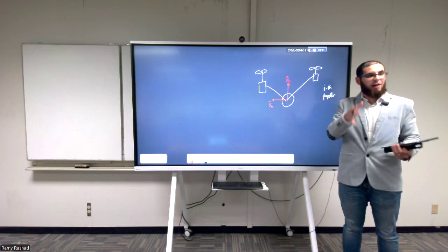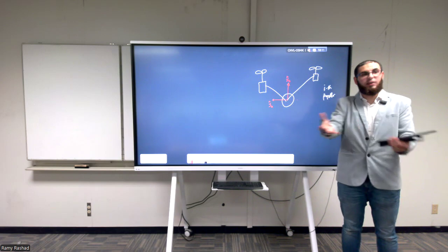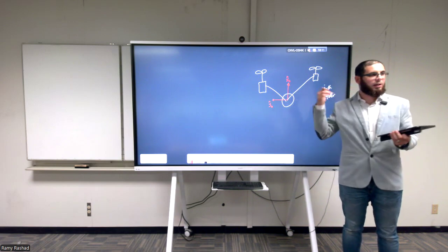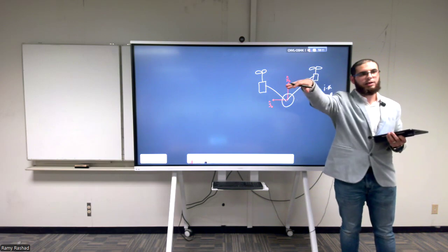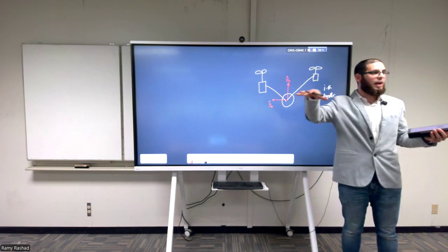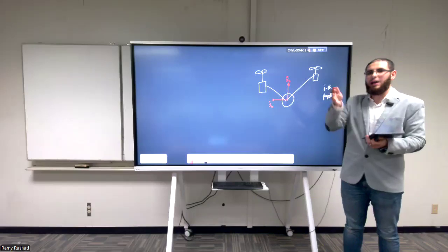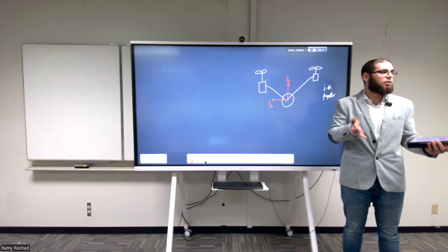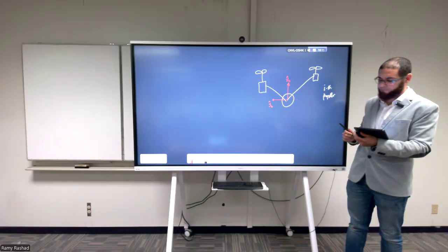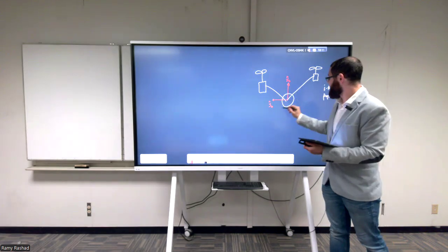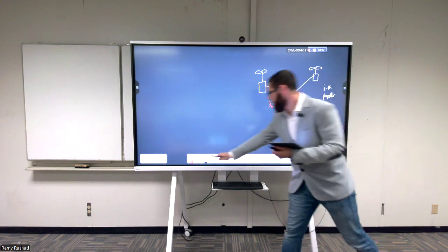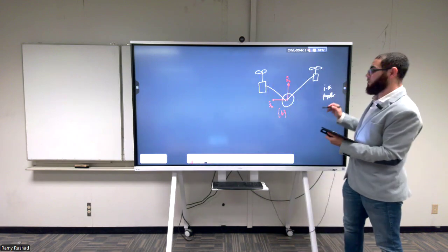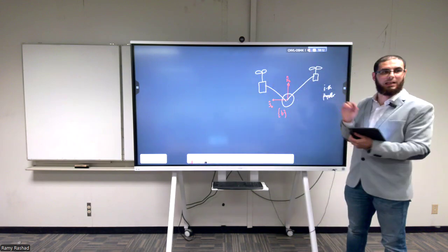The drone itself doesn't have any forward, because with multi-rotors you don't have a shape like with airplanes, which have to move in one direction. It can move sideways and in every direction in general. So we don't have this forward from the structure. You have to choose it. This is my structure, this is my forward. So this is the B frame. And we're going to have another frame here, which is the ith propeller frame. We're going to choose it as follows.